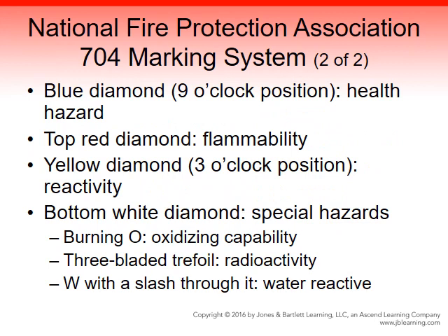The blue diamond at the 9 o'clock position has to do with health hazard. The top red diamond, flammability. The yellow diamond at the 3 o'clock position has to do with its reactivity. And the bottom diamond, white in nature, deals with special hazards, such as a burning O, which would mean oxidizing capabilities, or a 3-bladed trifold looking fan, and that would indicate radioactive material.